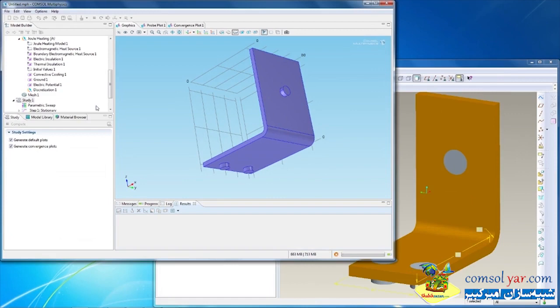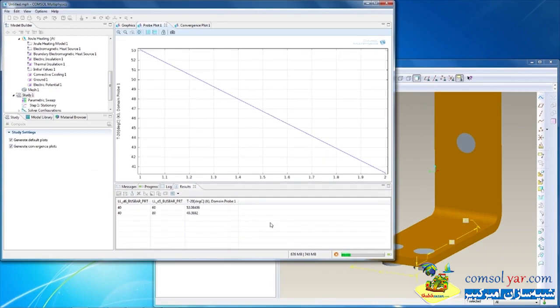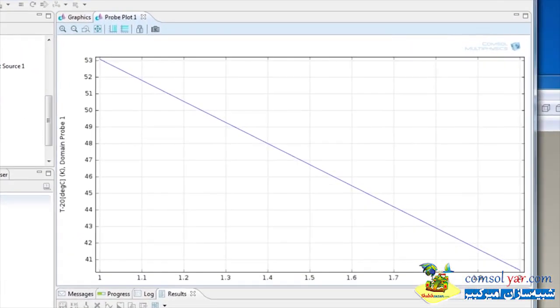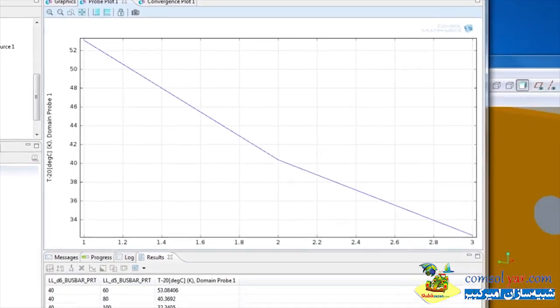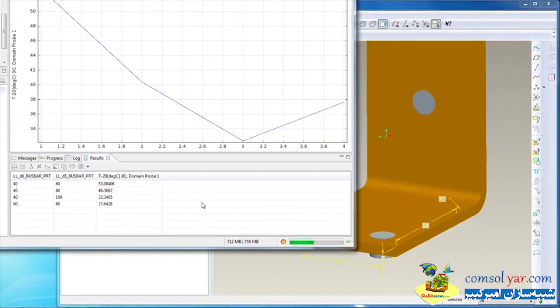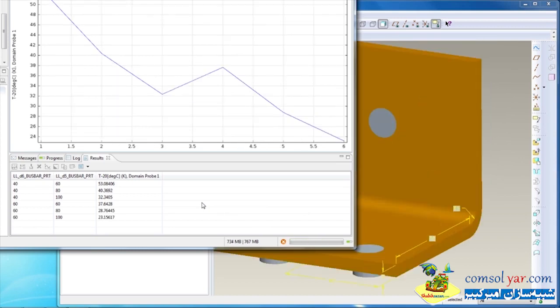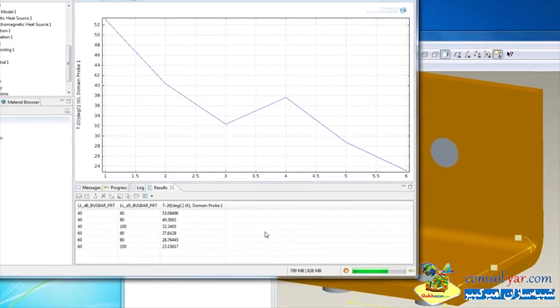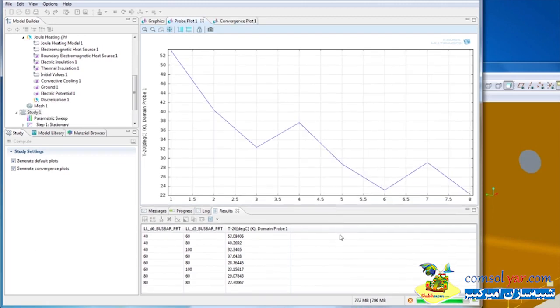During the sweep, COMSOL solves the model for each parameter combination and updates the results table with the evaluated temperature increase. I can also follow this process in a plot. For each new parameter combination, the values are synchronized with ProE, where the geometry is rebuilt and synchronized to COMSOL. Back in COMSOL, the sweep is almost done, and I can see how the temperature increase lowers for the larger dimensions of the bus bar.